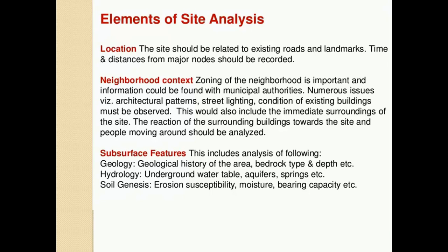Then subsurface features. This includes analysis of the following: geology, geological history of the area, bedrock type, depth, etc. Then hydrology: underground water table, aquifers, springs, etc. And then soil genesis, erosion susceptibility, moisture bearing capacity. Now, after that we will see one by one.